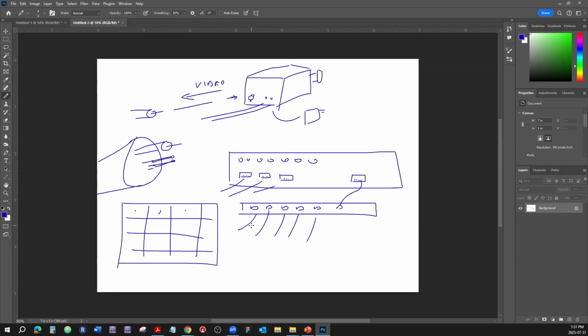Then they have the IP addresses. Those cameras do have the IP addresses or MAC addresses, but mostly for the IP. And then you have to manually go into the programming of the DVR or NVR and tell which camera, based on the IP address, you want to have on this square, that square, and so on. So there are different ways of placing it.